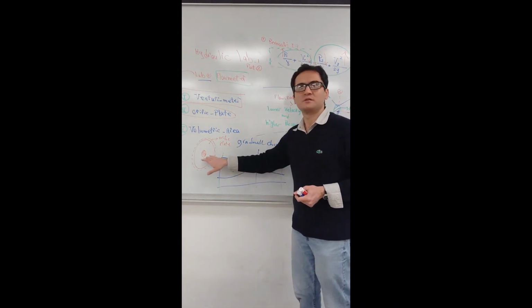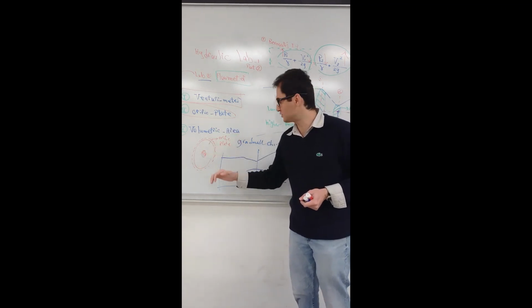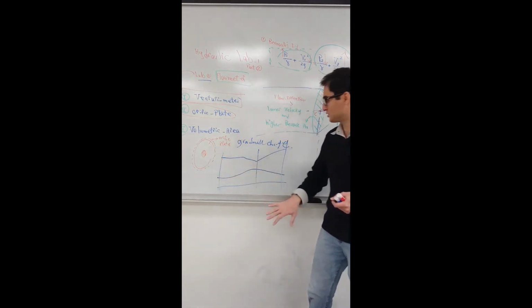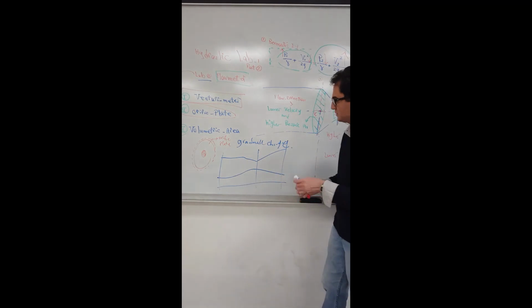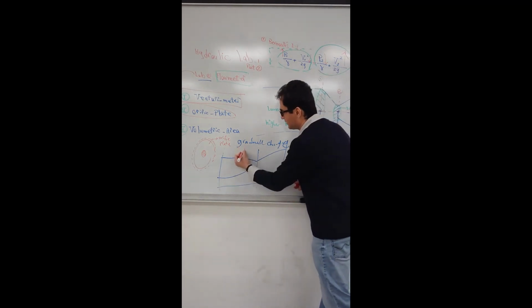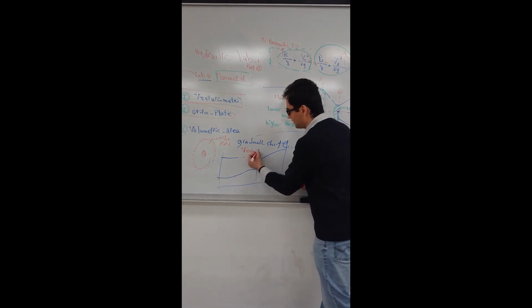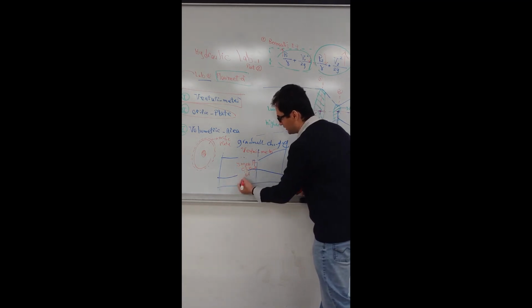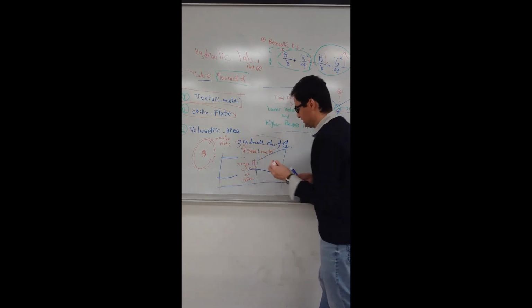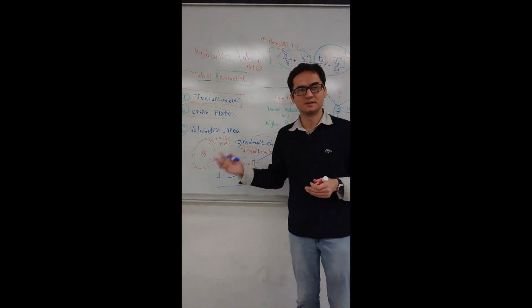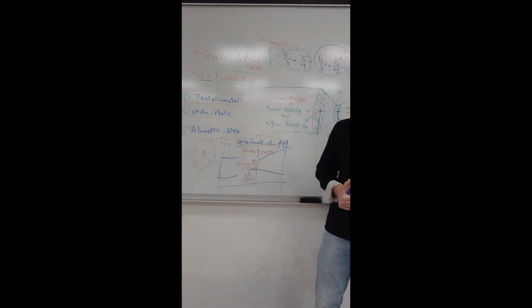So we expect to see a higher drop in the orifice plate in comparison to the venturi meter, where there is a smooth change of area, not a sudden one. So head loss should be lower.